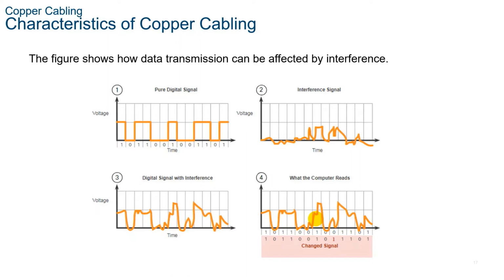The susceptibility of copper cables to electrical noise or electronic noise can be limited using these recommendations. Select the cable type or category most suited to a given network environment. Design a cable infrastructure to avoid known and potential sources of interference in the building structure. Use cabling techniques that include the proper handling and termination of the cables.